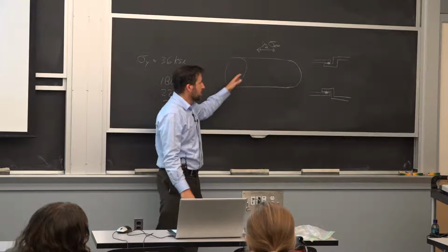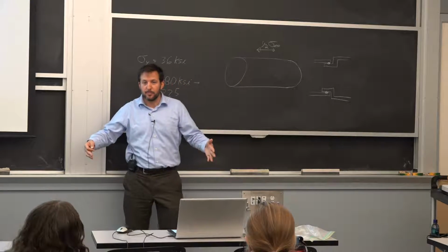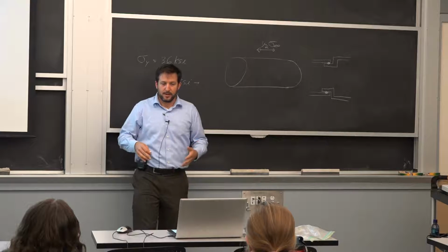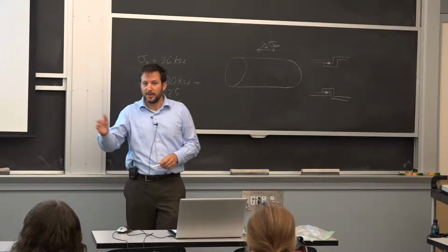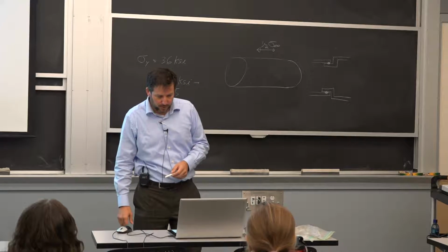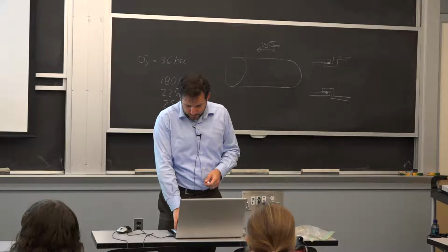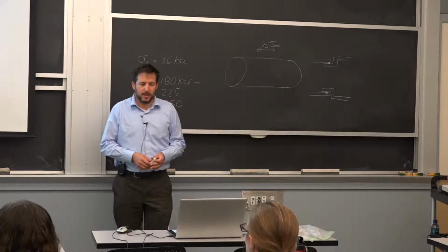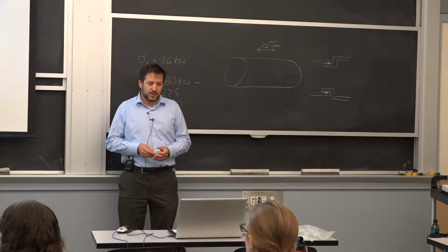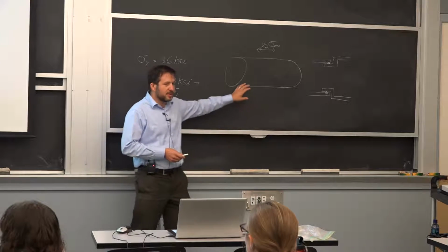So when you get to a turn, you have all these restraint blocks, and it's a pretty sophisticated system because you have more than 100,000 pounds at each joint being transferred or not transferred. The leak we had here in Massachusetts from MWRA was not the cylinder itself.